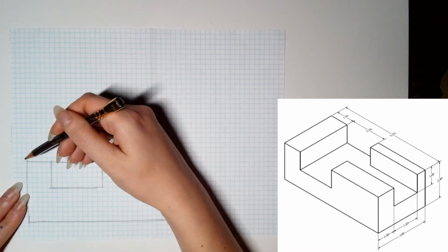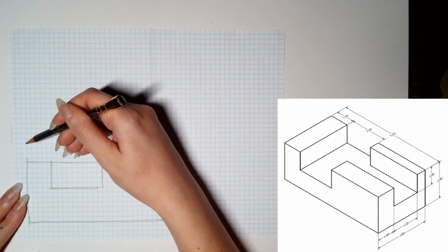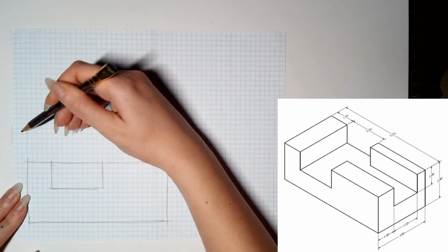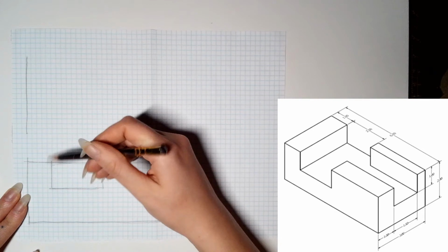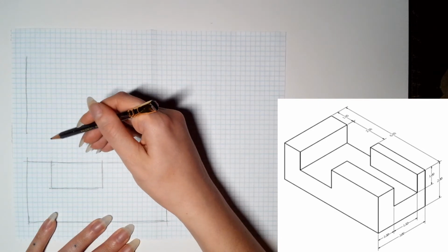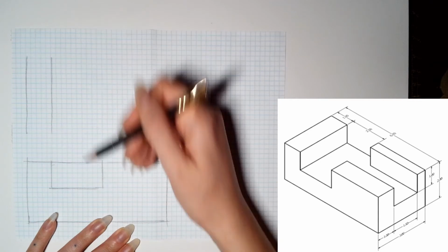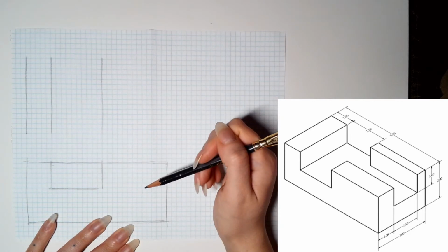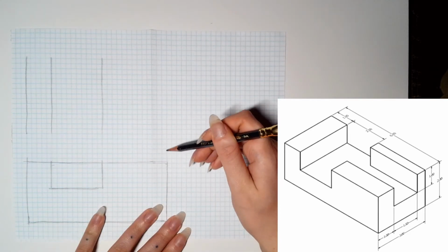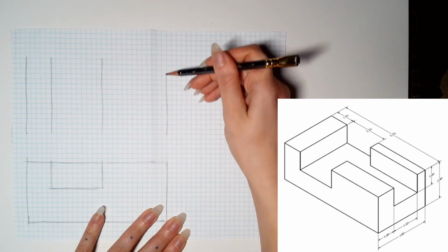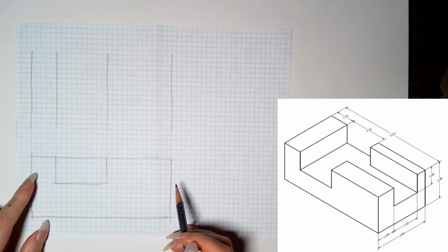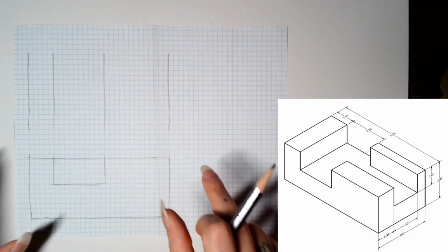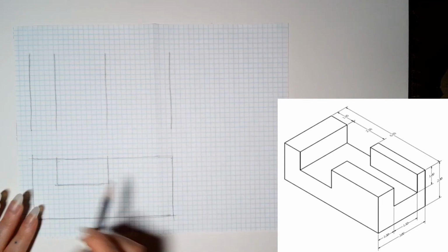So for my top view, a lot of times when I'm projecting these guidelines, I don't draw them all the way up. I just eyeball it to where I want it to be, and then I'll start projecting the guide, because otherwise it will be a lot of line work to erase. So I'm just giving myself a lot less work to erase. And I'm just guesstimating a good depth. So it has a depth of 3, and I'm saying, well, if that was 6, that seems about 3. But again, I'm not aiming for perfection in this sketch.